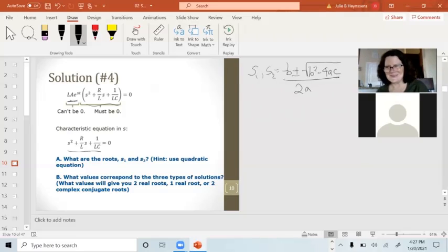Okay, yeah, and I wrote it. I was teaching 325, the advanced engineering math class. I gave an exam and somebody asked me what the quadratic equation was, and I felt sorry enough for him at that point. I wrote it on the board, and then he looks at me and goes, what's A, B, and C? So I will tell you, A is the coefficient of the S squared term. B is the coefficient of the S term, so A is 1. B would be R over L, and C would be 1 over LC. So we plug those in, and we get S1 and S2.